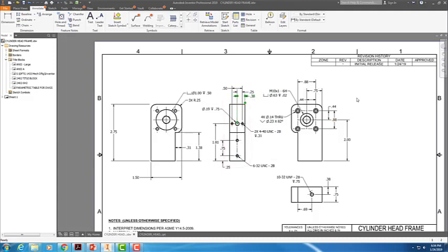Kind of... Alright. You guys see anything else? On the far left. Far left. Oh, thank you. Good eye. And that's way far out there. There is no maximum space, but there is a 0.4 minimum space for your first dimension away from the edge of the part. So this is really not too close. Just don't crowd the part. I've never had a checker come up and say this is not 0.4 inches away from the part.